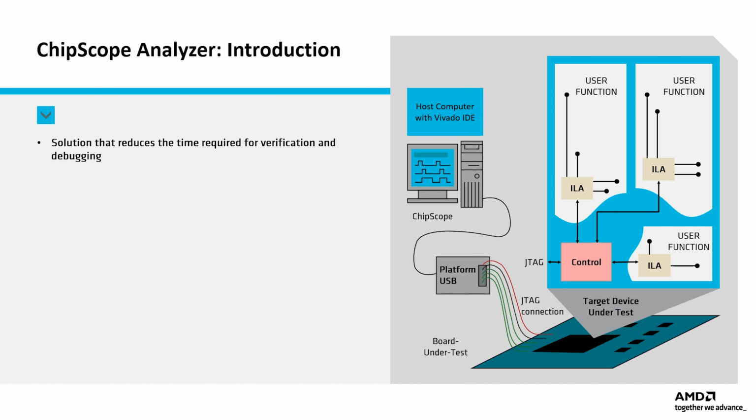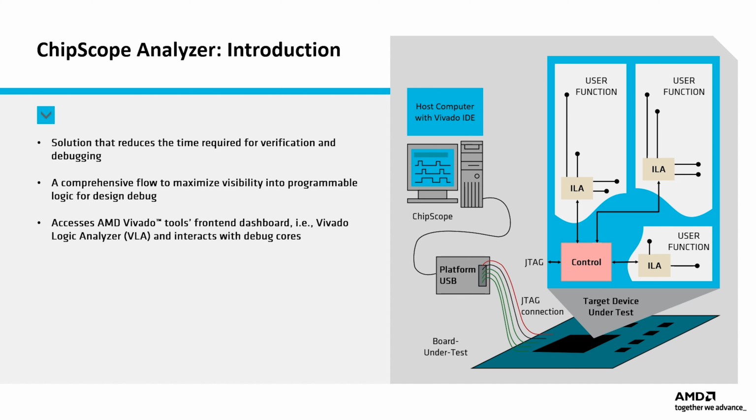AMD provides a ChipScope debug solution, which reduces the time required for verification and debugging. ChipScope provides a comprehensive flow to maximize visibility into programmable logic for design debug during system operation. It accesses Vivado Logic Analyzer, VLA, which is a Vivado front-end dashboard that interacts with debug cores in your design.